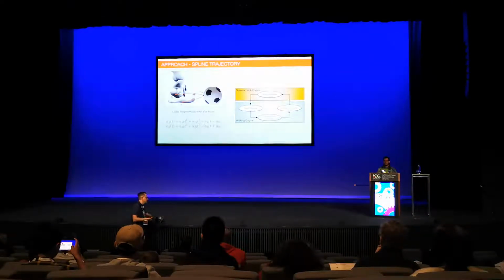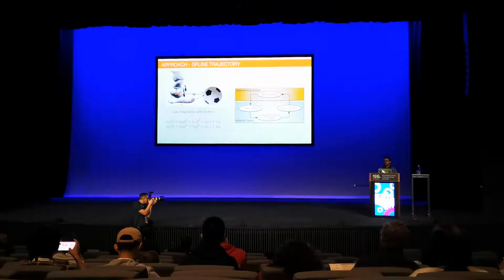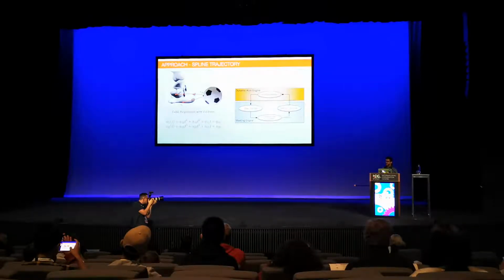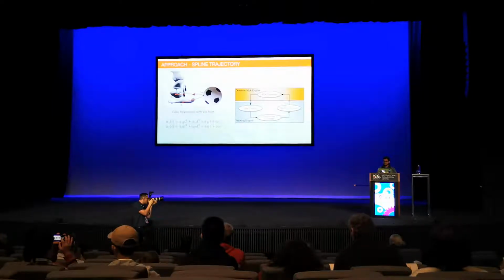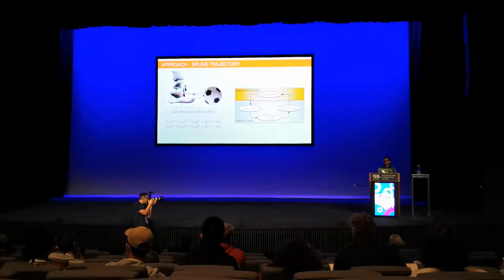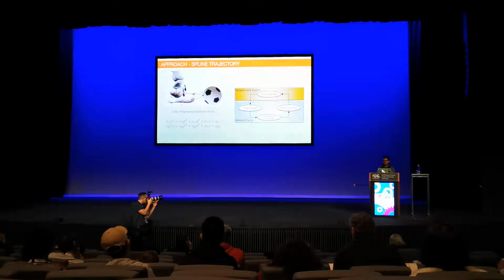The spline trajectory generator utilizes different splines to generate kick motions. The spline used for this research is made of cubic polynomials with a via-point acting as the knot for both polynomials. The coefficients can be used to generate constraints, and the constraints of the kick trajectories are used to control the position, velocity, and acceleration of the kick. It is also used to control the height of the foot from the ground at the via-point. The figure at the top left shows an example of a walk kick trajectory.